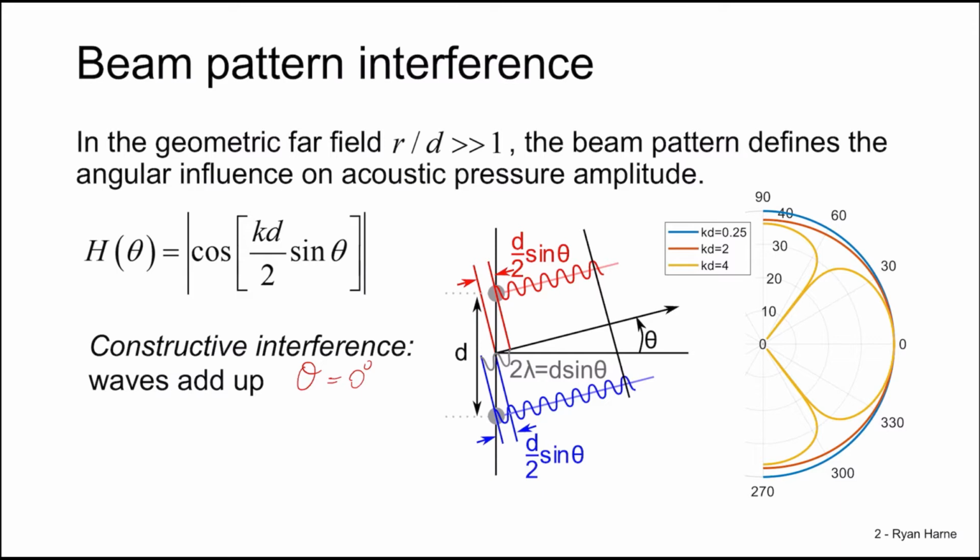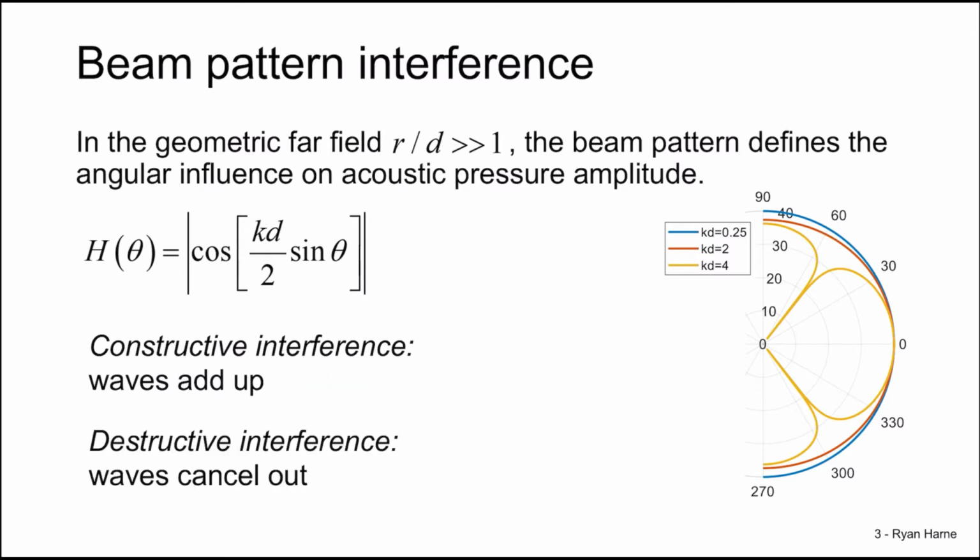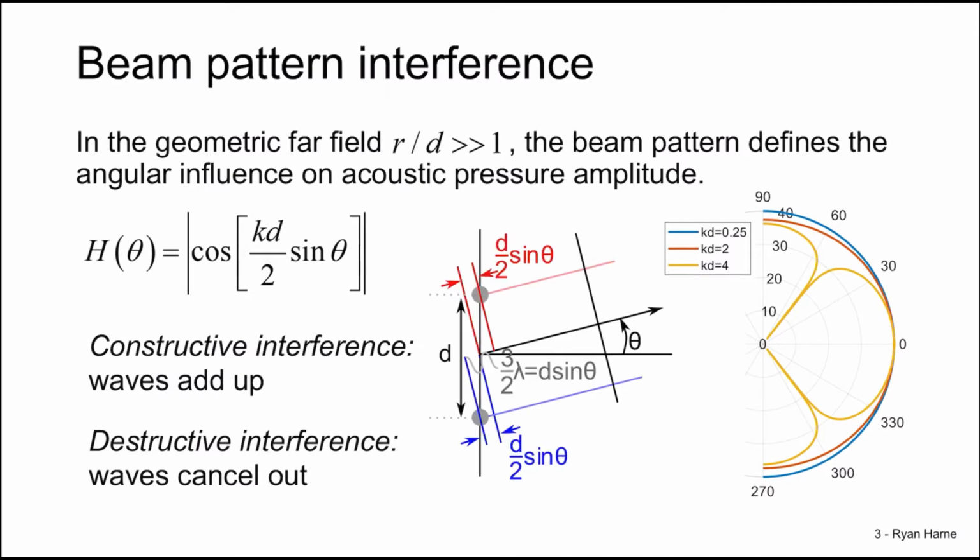This would be a case given the frequency and wavelength lambda involved, where we would have a side lobe for this angular location. The alternative, where nulls and nodes occur, is destructive interference. It is due to the fact that the waves are canceling out. Now take, for instance, 3.5 wavelengths equal to d sine theta. In other words, they're equal to the angular distance between the sources with respect to the field point. In this case, one source has a negative value at an instantaneous location in space, whereas the other has a positive value. So this would be the case of creating nulls, also called nodes.